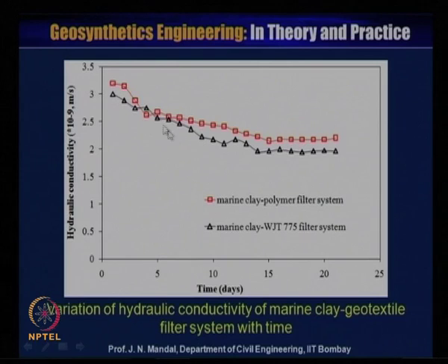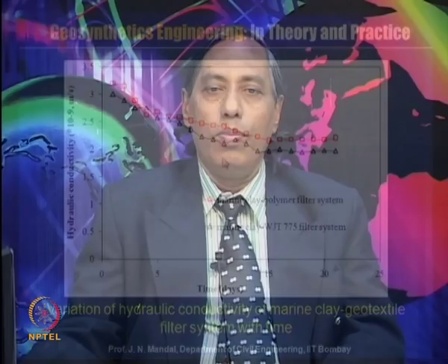You can see how the hydraulic conductivity is decreasing with increasing time in days, and then after about 15 days it remains constant. So, these also satisfy the criteria for both cases, the polymer filter system as well as the natural prefabricated vertical drain system, while in both cases marine clay has been used.